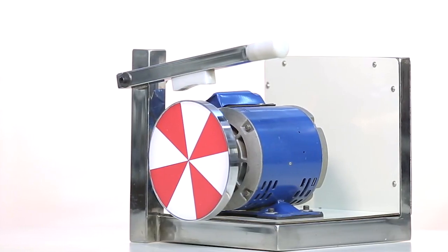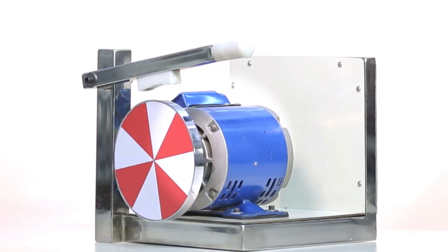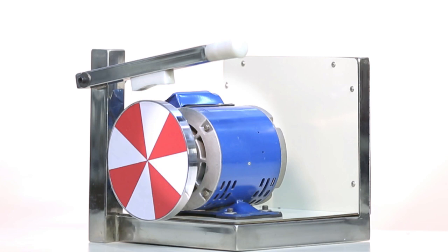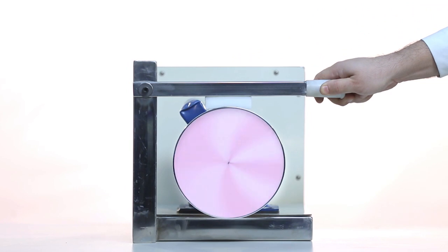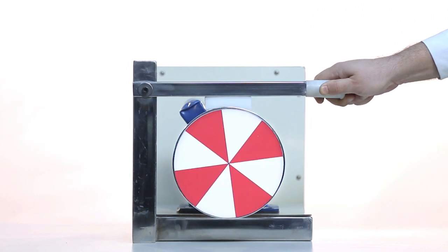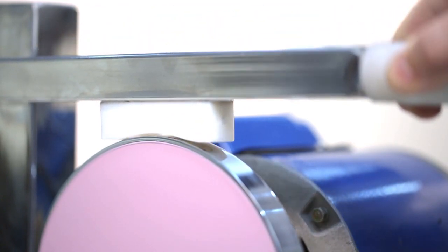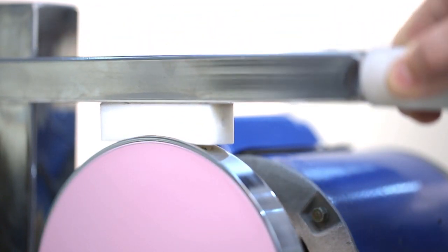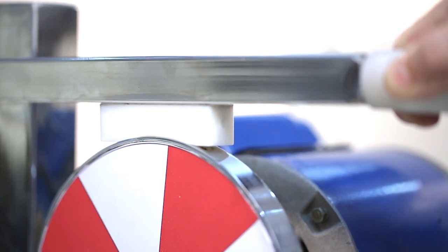Now, let us take a closer look at how to stop a motorcycle using a small experiment. When something is forced against the rotating rotor, the rotor decelerates and eventually stops. This is because the slipping surfaces generate friction and the rotor's kinetic energy is converted into thermal energy.